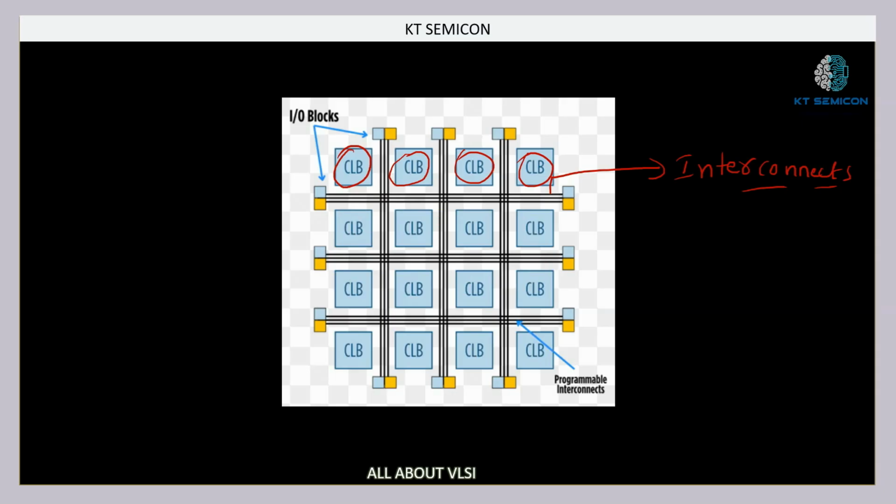Now, for example, if our FPGA wants to act as a UART controller, which is going to control a UART frame for filtering or removing any packets, that particular logic it can implement. Let's say if it needs to act as a counter for counting the number of clock pulses, it can act. If it needs to act as a finite state machine, as a simple traffic light controller, or a vending machine, it can act. How that configurability is achieved by the FPGA is nothing but using these configurable logic blocks, and they will be connected using these interconnects.